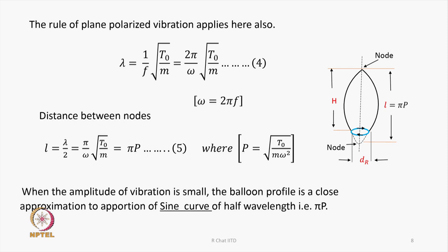What we have to always make sure is that this node, the bottom node, should not be generated above the ring, or we can say, so that h is not less than L. If h happens to be less than L due to any reason, then the yarn is going to touch the surface of the bobbin, and that may lead to basically finally breakage.